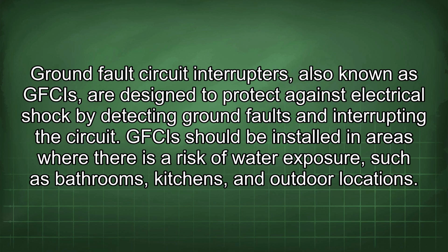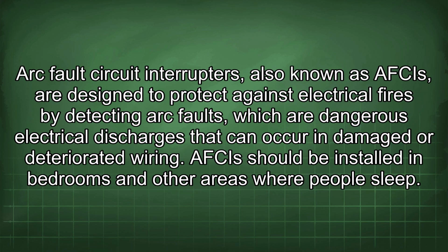Ground fault circuit interrupters, also known as GFCIs, are designed to protect against electrical shock by detecting ground faults and interrupting the circuit. GFCIs should be installed in areas where there is a risk of water exposure, such as bathrooms, kitchens, and outdoor locations. Arc fault circuit interrupters, also known as AFCIs, are designed to protect against electrical fires by detecting arc faults, which are dangerous electrical discharges that can occur in damaged or deteriorated wiring. AFCIs should be installed in bedrooms and other areas where people sleep.